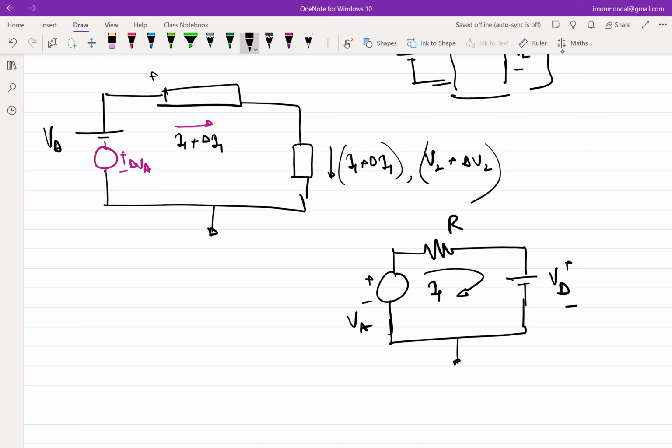So if we conserve the voltage drop across an element, then the rest of the network shouldn't bother as far as solving KCL and KVL is concerned. If you are solving KVL, you are going around the loop, checking for voltage drops, and I am preserving the voltage drop by replacing an element with a voltage source that corresponds to the voltage drop it was originally giving. You don't seem convinced.